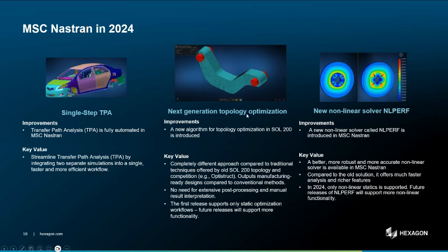It's then also possible to do better topology optimization. It's effectively the same algorithms and the same method as used by generative design. So I'm changing from this to generative design. It's just one parameter change. And if you want to, you can add additional things like draft angles and so on, so you have a bit more control there.